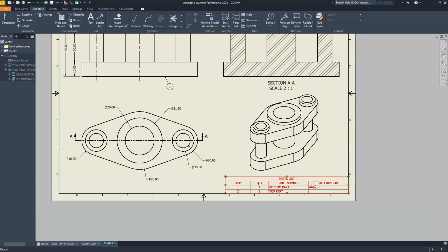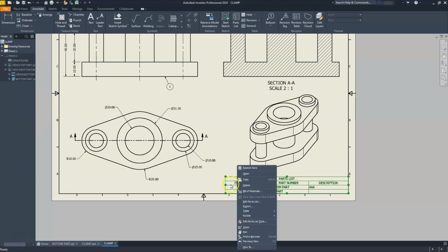But another quicker method of doing that is if I come to where it says, let's see, the annotation one, and I'm looking for my parts list, if you come to this bill of material and do a right click, and then you choose the word bill of material, this actually opens up all of that metadata that's in each of the parts.